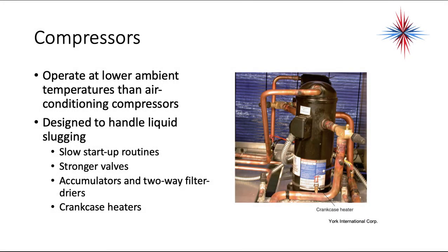The compressors in heat pump systems operate at lower ambient temperatures than air conditioning compressors. They're designed to handle a little bit of liquid slugging. Most of them will be scroll compressors now. They have slow startup routines, they have stronger valves, and with the accumulators they have two-way filter dryers. If you ever replace a filter dryer in a heat pump system, make sure it's called a bidirectional or two-way filter dryer. They will usually have crankcase heaters installed. If you look here, you'll see a little band around the bottom of the compressor. That's a crankcase heater.